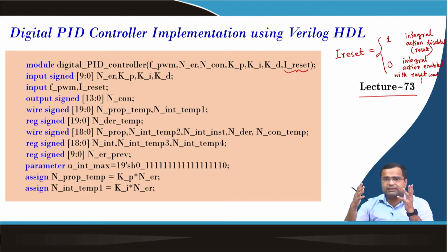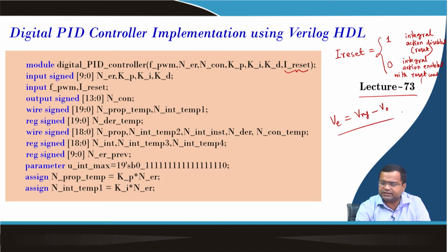As per the pulse skipping logic, if the output voltage just falls below Vref, then the charge pulse starts, the voltage goes above Vref and then it starts discharging. So all the time the output voltage is more or less above Vref, and if we enable the integral action, then the error will be negative all the time, because error is Vref minus V0. Since V0 will always be above Vref, this negative quantity will be accumulated and can cause a wind up problem, and also during transition the controller output will be very much negative. So, you want to avoid that.